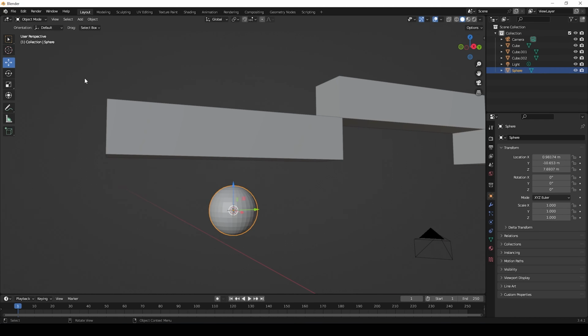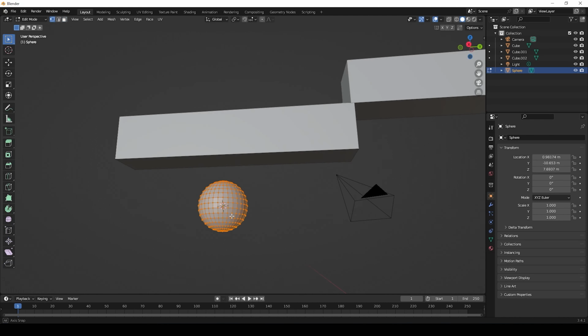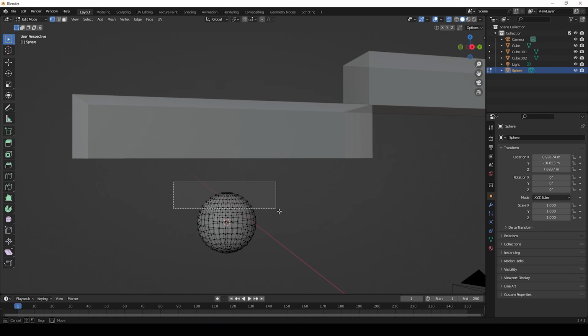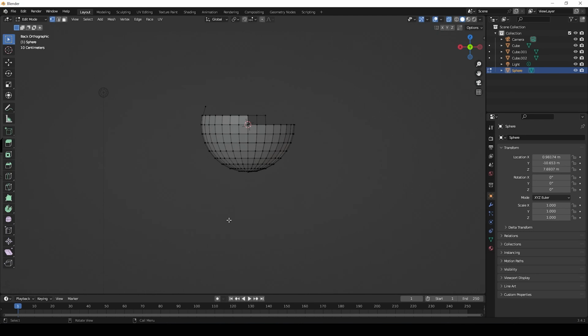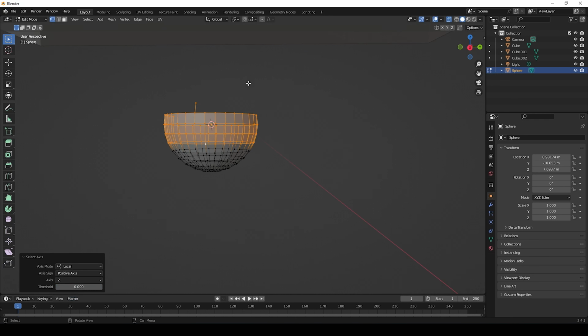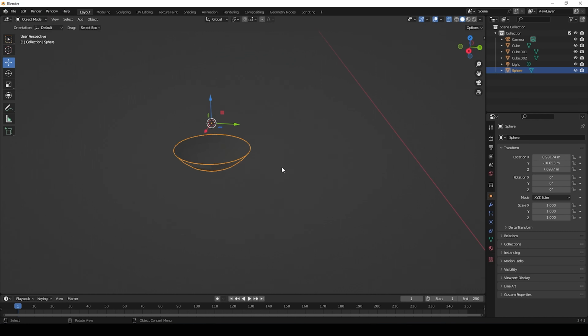I'm going to click that UV sphere, hit Tab to go back into edit mode, and we need to turn off faces and go back into nodes here. And now we can also turn on X-ray mode so that we can see through the object. Just select some nodes here, hit X, delete all those vertices. Okay, so we're slowly building this shape down into our eventual antenna here. I like a little bit of precision, so I'm going to select this node here. I'm going to go to Select, Side of Active, change the axis to Z. Everything positive of that node will be deleted, and hit X and delete our vertices. I think that's looking pretty good. Let's go ahead and just call that our standard antenna.